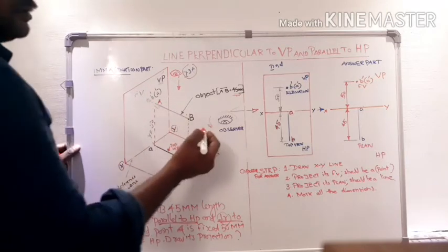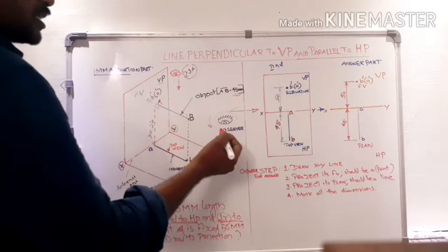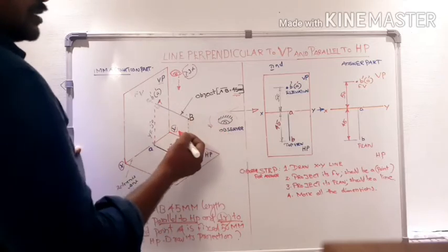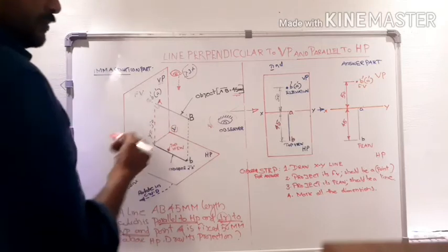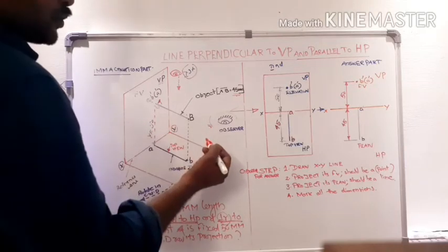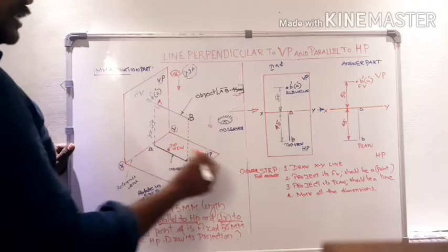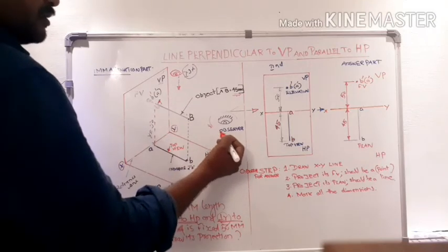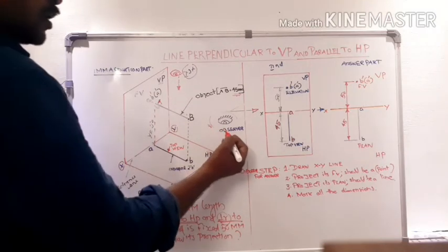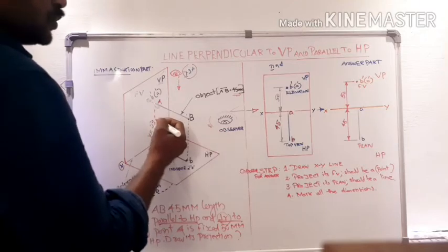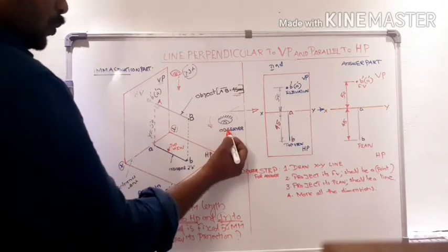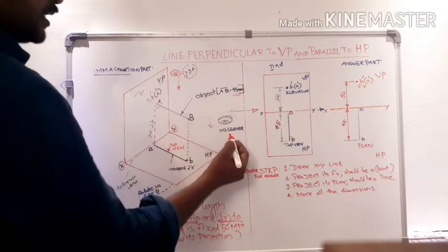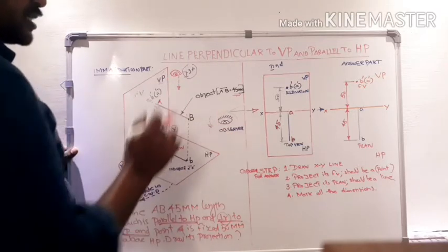Now we have to draw its views, that is, draw its front view and its plan. First we have to draw its front view. For that we can fix the position of the observer with respect to the quadrant. We know that the observer always stands at the right hand side of the quadrant.